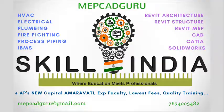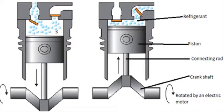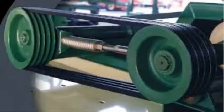Hands-on experience. Compressors used in heating, ventilation and air conditioning. Compressor is used to remove the heat-laden vapor refrigerant from the evaporator of the air conditioning systems. In layman's terms, the compressor compresses the vapor into a smaller volume at high temperature. The external drive compressor has a crankshaft that is driven by a pulley and belt system. An electric motor can also be used to drive it directly.